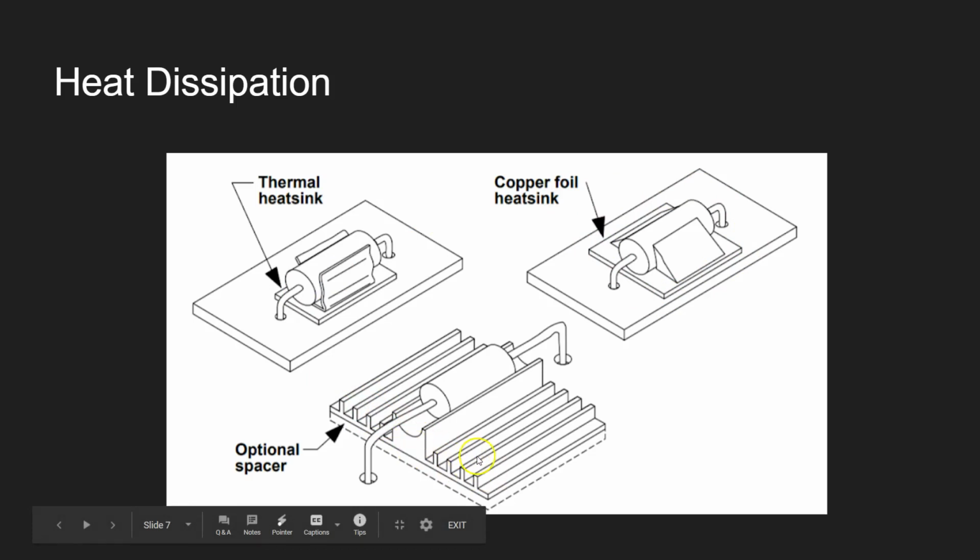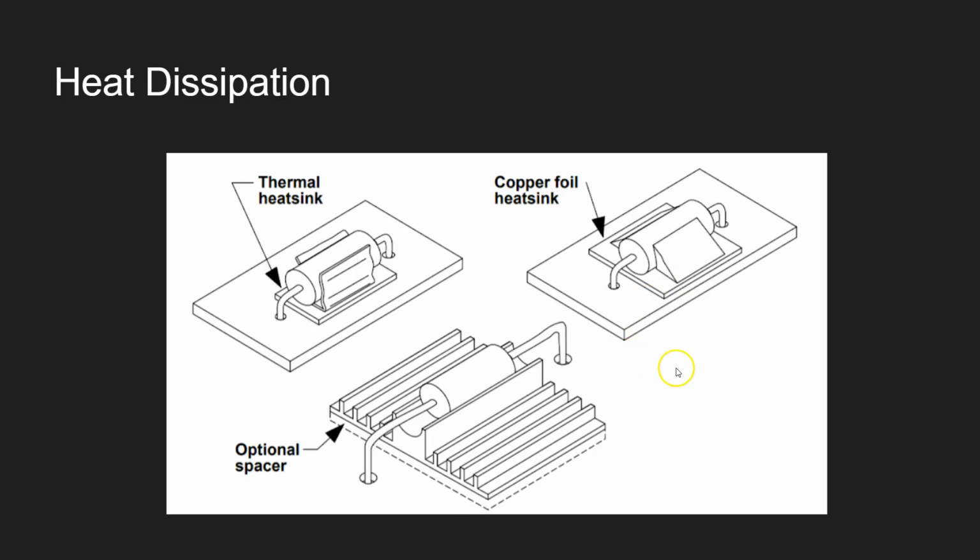There are different types of spacers which you can use in your printed circuit board. So heat dissipation may be obtained by having a gap between the board and the component, using a clamp or thermal mounting plate, or attaching a compatible thermally conductive material working in conjunction with a thermal bus plane to the component. We'll learn about these more in the coming slides.